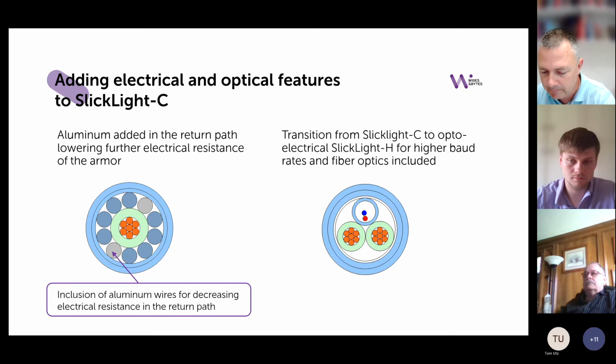So it's always, of course, a trade-off between these parameters: the size, the type of material, and the design, so mechanical and electrical features, of course. And in the right design, we actually have two high-temperature copper wires and one FIMT, in what I would call a star configuration. Here we have more benefits, actually. As you can see, more gap is included, so more void between these three stranded elements, which will further decrease capacitance.